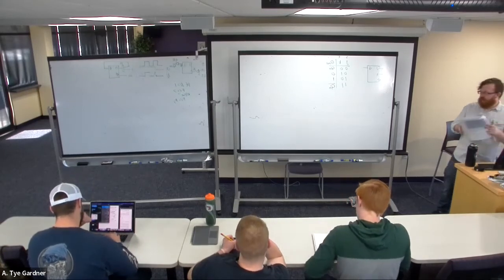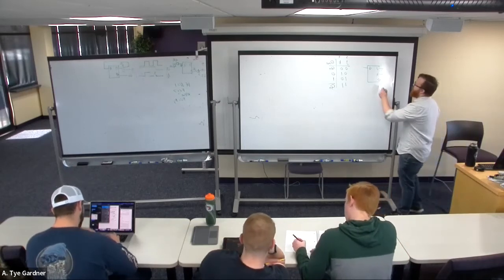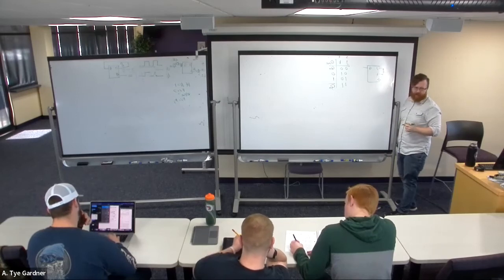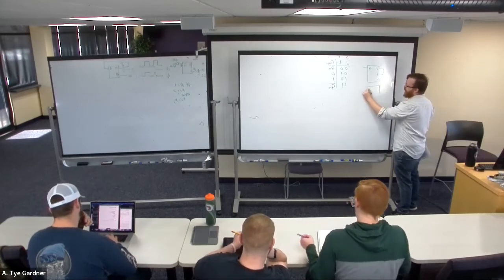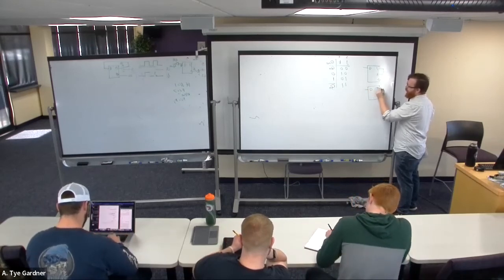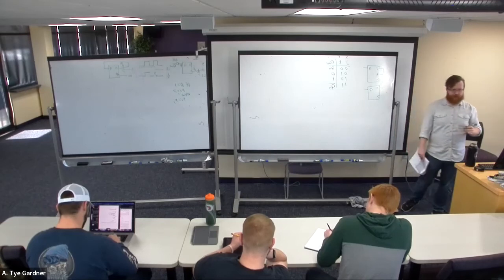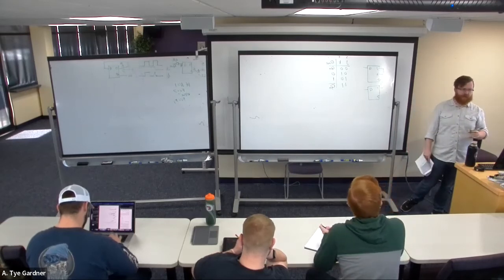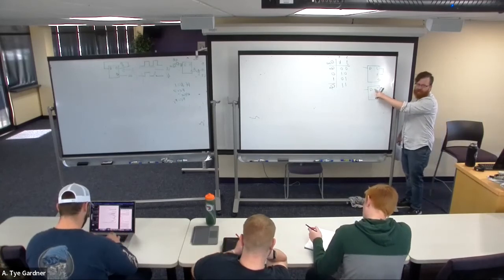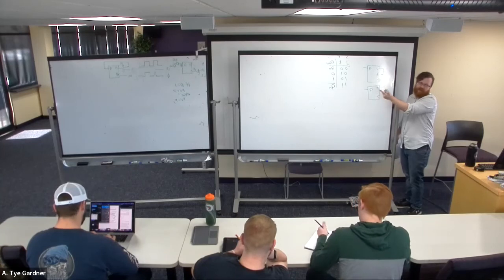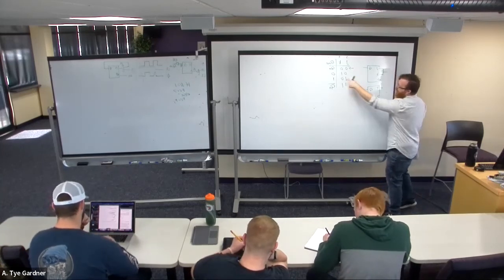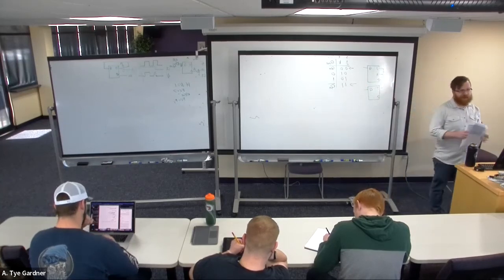There's a similar functionality, which is really nice: if you take both of the inputs and tie them together, like so, that makes a new device called a T flip-flop. A T flip-flop is a toggle flip-flop, because if T is 0, Q stays the same. If T is 1, it toggles, it inverts, right? Because it's just this row or that row. It can't be the middle two because they're tied together. So it's either toggling or not.